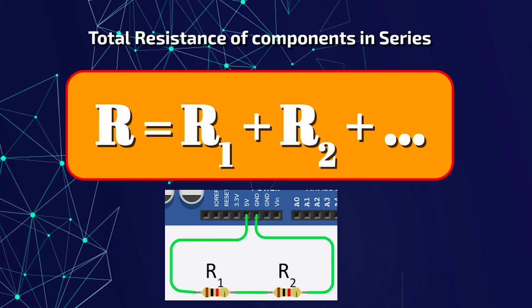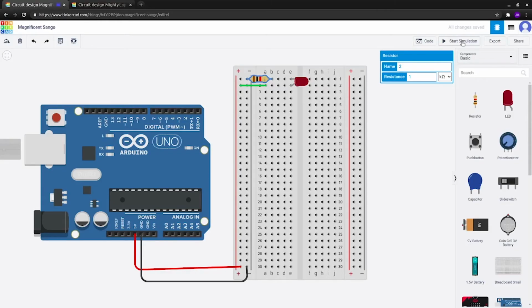The meaning of connecting something in series just means that the path that the electricity would have to take through one component is the same as the other component. As you can see here, you would have to go through R1 before you can reach R2, and before you can reach ground. Now when we run the circuit, we shouldn't get that warning anymore. And great, we lit up the LED without making it explode.